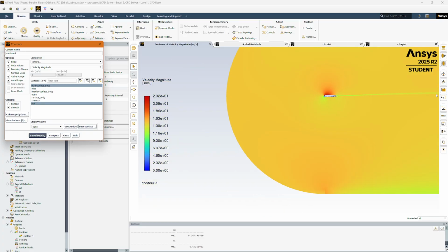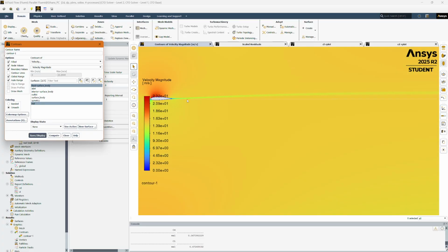The important bit about this, our wake angle, is coming up and off here. We're also seeing a growing boundary layer here as this air begins to detach off the surface of the airfoil. And as I grow my angle of attack, that's when I get further and further up. So it's very noticeable at 21 degrees. It's almost up to here as we approach stall.